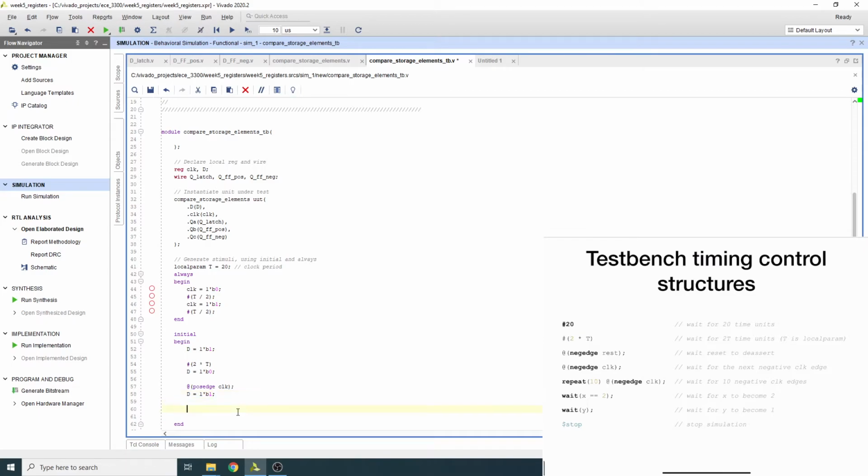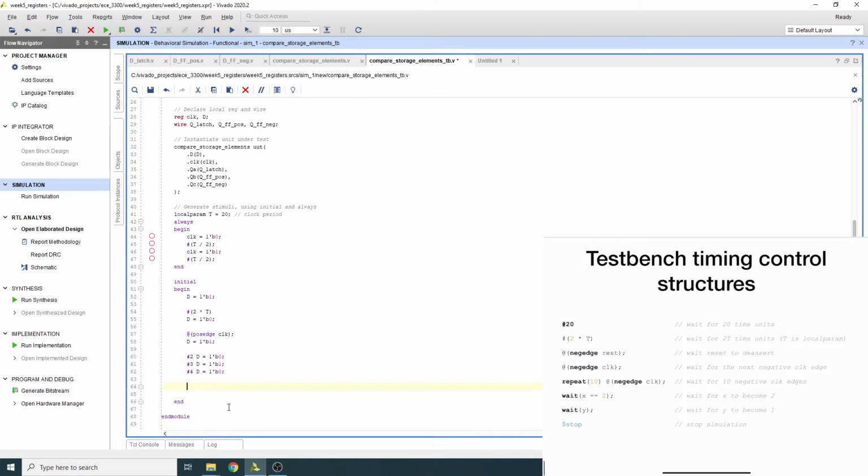And now here, what I want to do is use this old school one, which is let's wait for 2 nanoseconds. I'm doing this on purpose so that I'm changing it within a clock period, to show you how the latch is actually changing with the D. Remember, we're still testing latches and flip-flops, okay? And then here we're going to wait for 4 nanoseconds, D equals 1'b0.